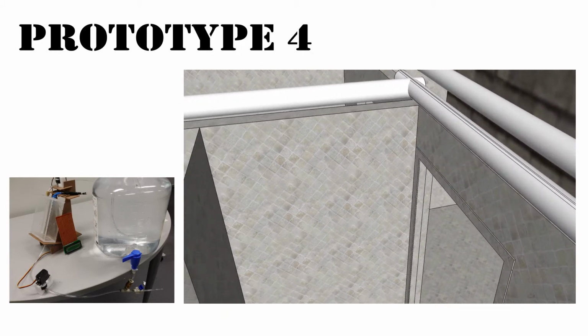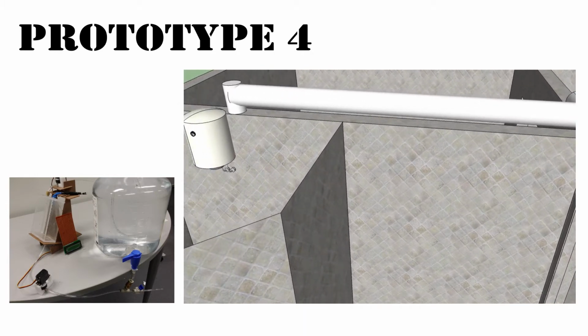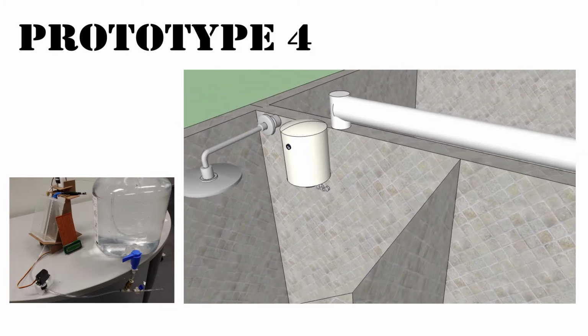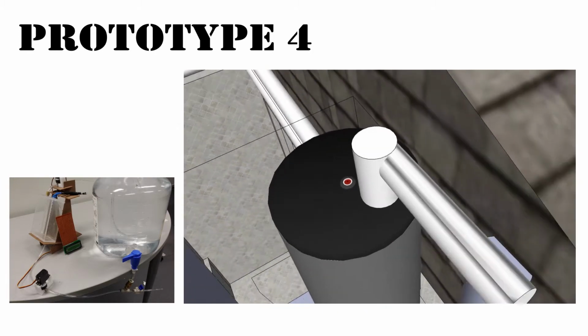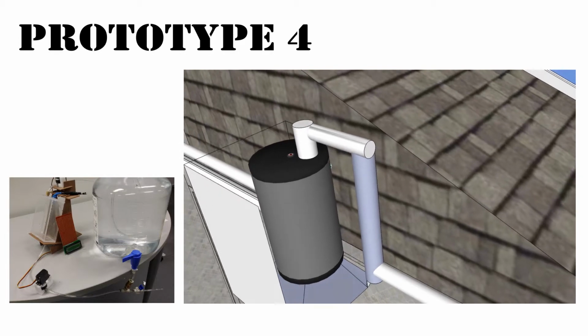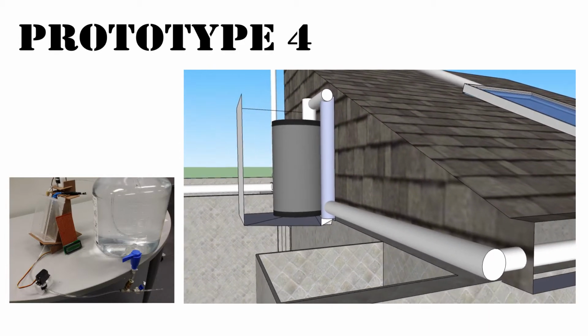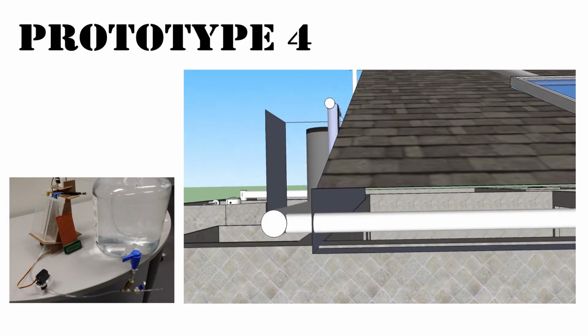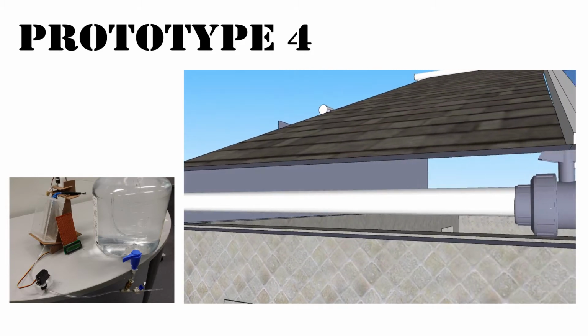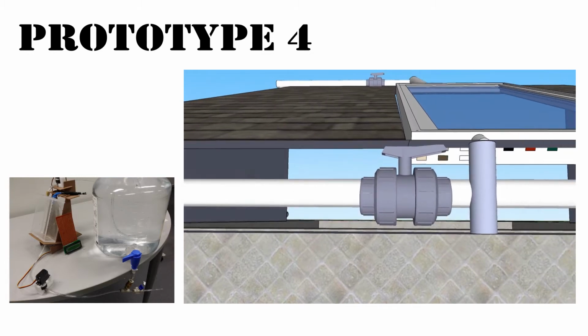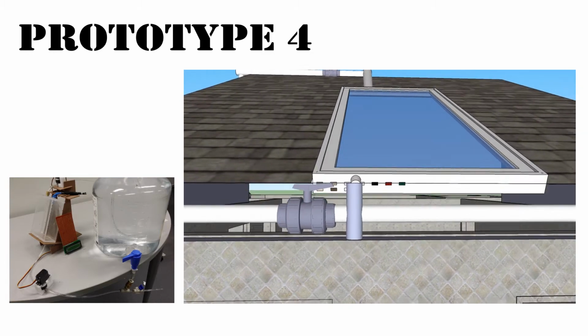The hot water in the storage container can be channeled to the bathroom by other pipes. The cold water in the storage container will sink and be channeled into the skylight water heater by another pipe to be heated up. Overall, the whole system will ensure a continual flow of water and ensure that the water will always be heated.